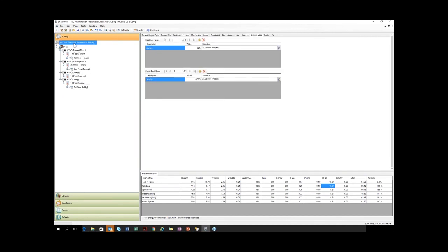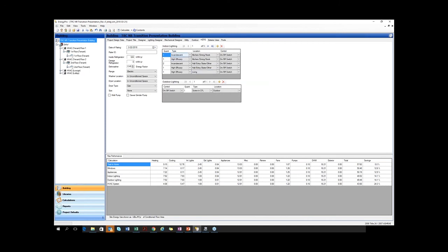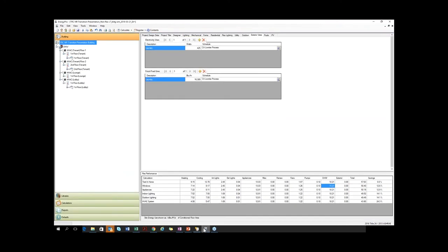What we're having people do generally in the multifamily upgrade program right now is in the HERS tab, you take an average of all the common area spaces and distribute that lighting equipment through the units. So the lounge and the lobby lighting is included in this HERS tab. Because the inputs are being accounted for in the HERS tab, we just want to distribute it through all the spaces in the model.